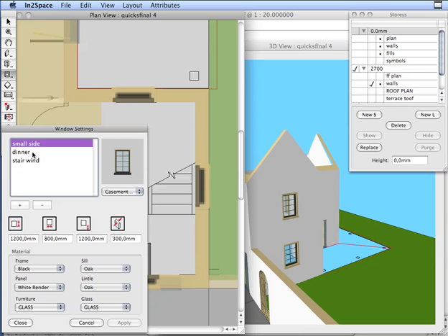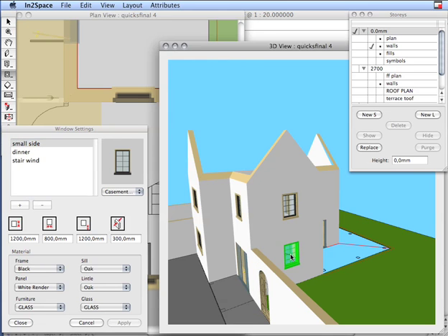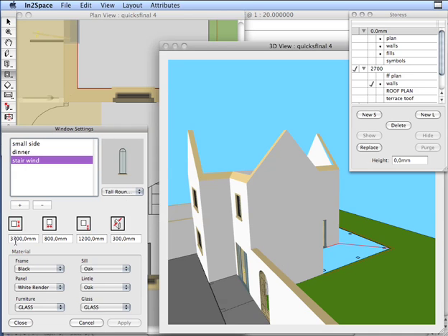First of all, let's show you how we can bridge the gap between two walls, or two stories should I say. Currently we can't punch a window in a lower story that pokes through to an upper story. We shall remedy this before too long in later versions, but for now we have a fairly easy and quick and simple workaround. First thing to do is delete our two windows, and we're going to insert this tall window.